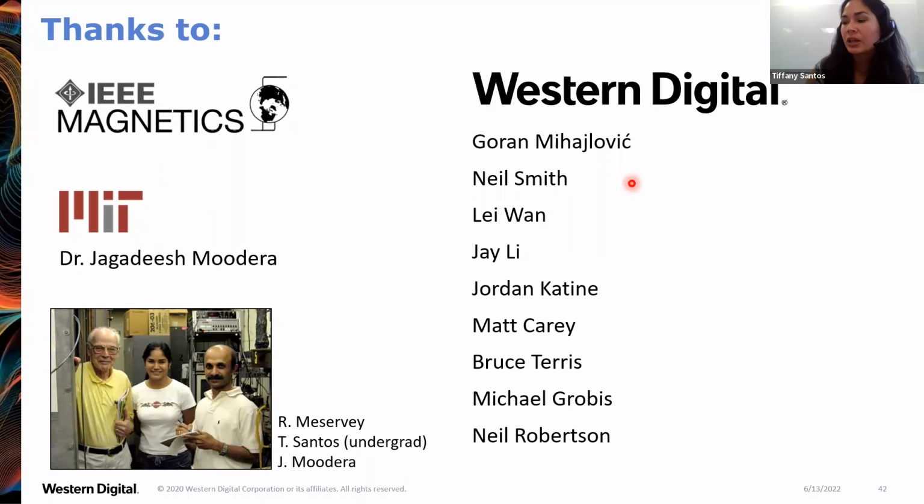Now, inserting a layer at that cobalt iron MgO interface that's needed for high TMR, you can get some interesting effects that help PMA there, but it will kill your TMR. So can you insert something there that will not destroy your TMR? We used tungsten as an example here, but there are some detrimental aspects to it that we're trying to get around. We're open to other things that could help us enhance PMA further in the free layer.